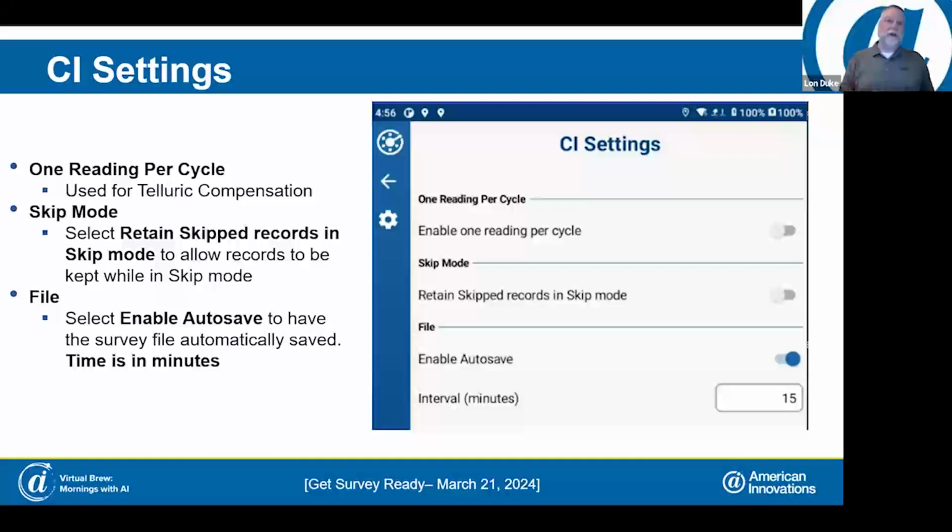You'll put in a gap, and then you go across and put in another gap. And what that's going to do is it's going to rubber band from that gap back to your last flag, and then your end gap to your next flag. So in the case of a 100-foot flag, you'll still have that 100 feet. So yeah, it'll keep all that stationing.